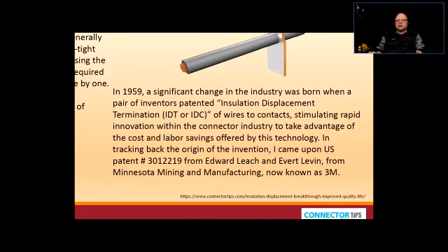cable? Well, if you were doing soldering or crimping, soldering would involve stripping and basically doing all the prep that has to do with the soldering, and then we will have to solder them one by one. So 50 connectors, 25 pairs, 50 connectors. The time that would take to do that would be significantly longer than doing the punch down IDC type of connection. All right, same as crimping.